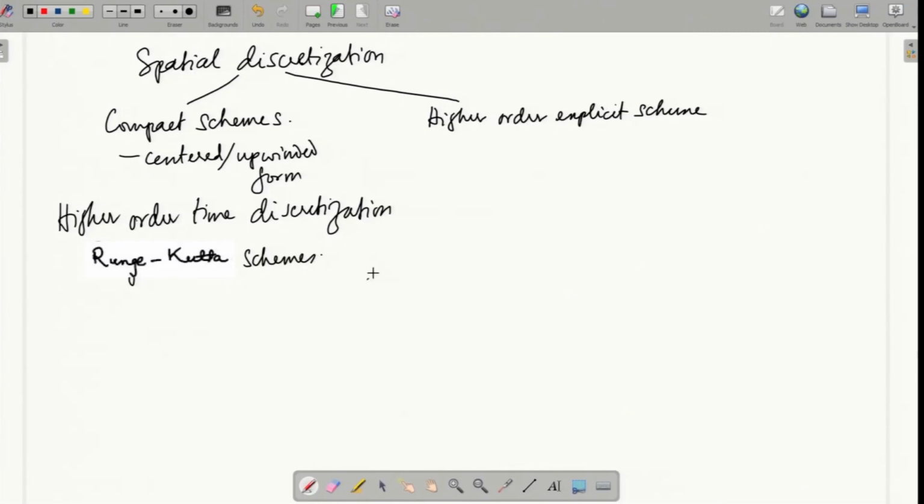And then you would have superior accuracy as well as enhanced numerical stability if you are using Runge-Kutta schemes, but typically for primitive variable approach in incompressible flows, that would mean that you would have to carry out the pressure velocity corrections a number of times within a given time step, because Runge-Kutta schemes split up one time step into several sub steps.